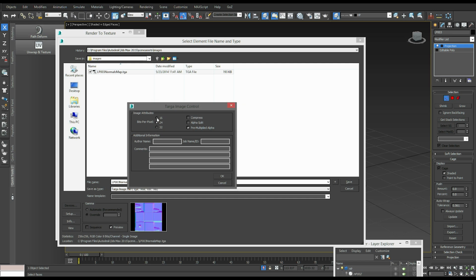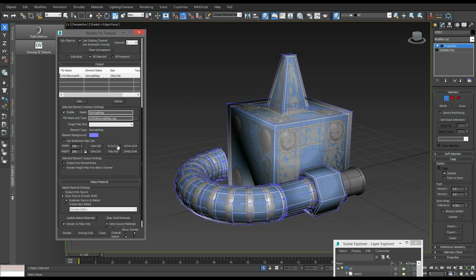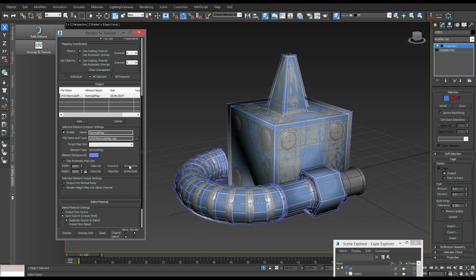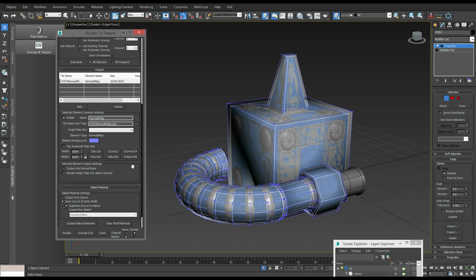So once we got this set up, I just click OK, and that's it. Like I was saying, as far as what size texture you want to use, usually 1024 will be fine. And then your final bake, you can set to 2048. You can also plug in a straight numerical value. So if you're baking out to like 4K, they don't have that here, but you can just type it in there. So we'll set that back to 1024.